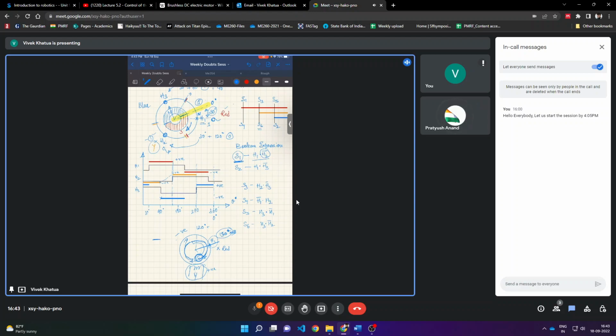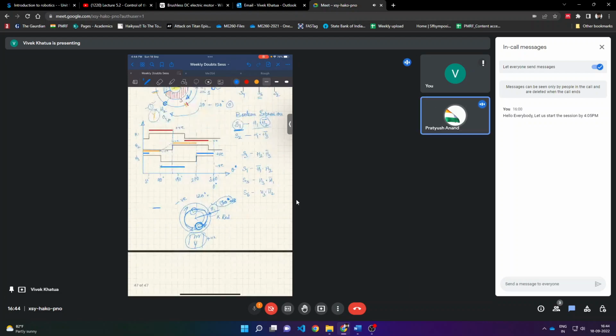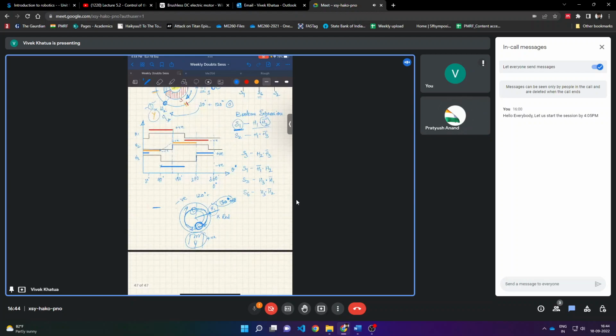If you take a little more than 30, the moment you are at 60 degrees, it will come to H2. But here you know that this is also 30, this is also 30. The moment you have gone 30 more, you are leaving H1. So that is where it should be H1 dot H2 bar, because just after 30, this 60 degrees that we have made, 30 plus 30, just after that, H2 is going to give me a positive signal, and H1 is going to